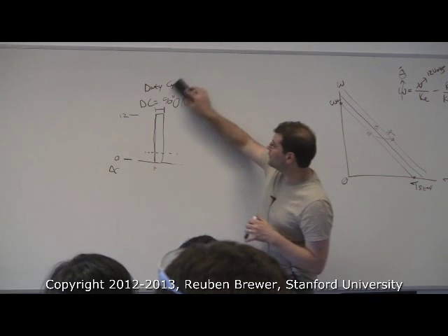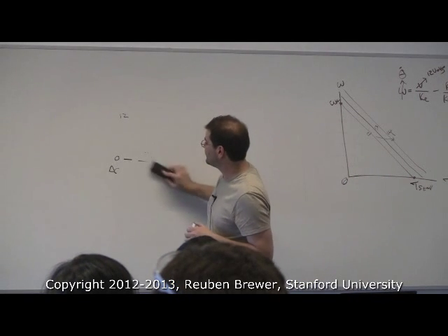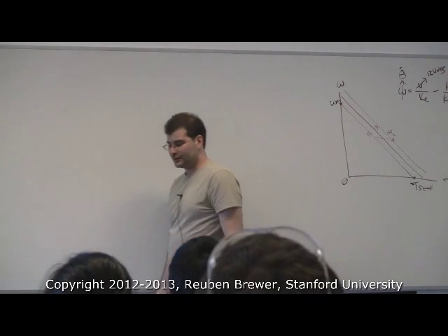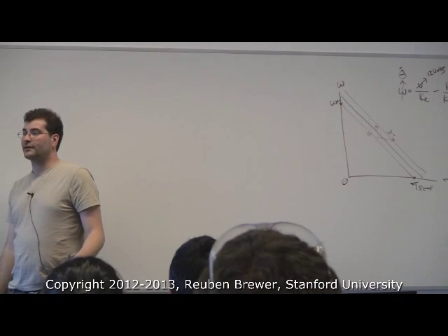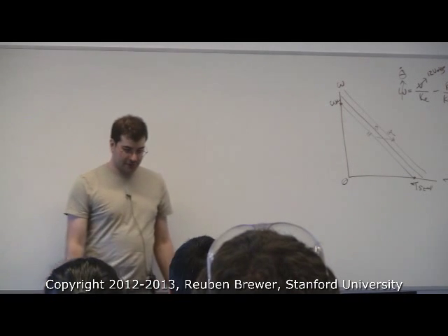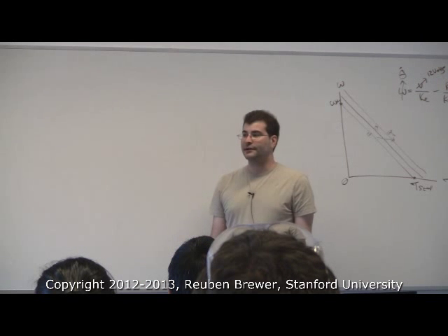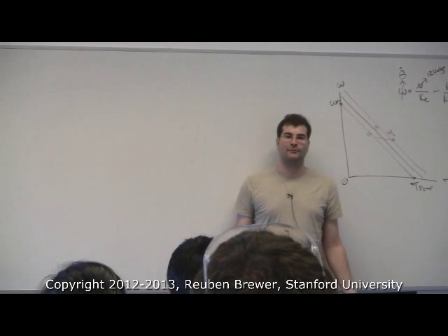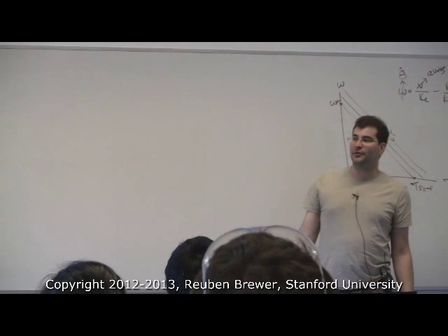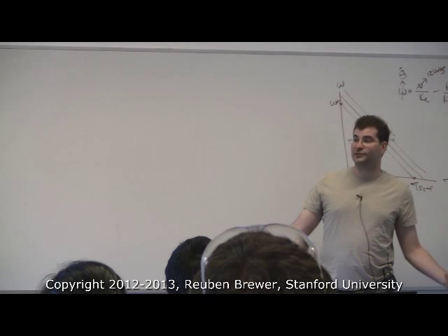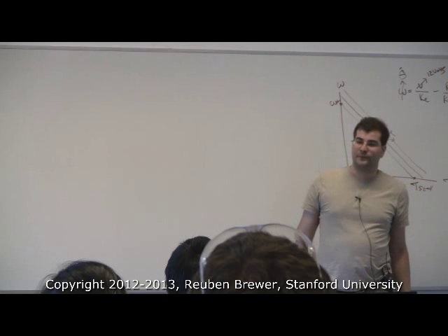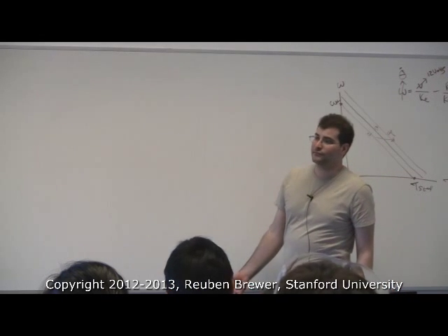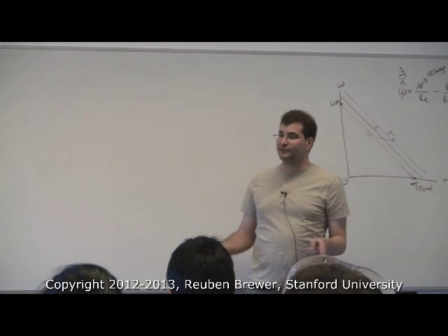The reason why I'm being a bit glib about that is typically you're going to be somewhere around, I think, 20 to 48 kilohertz in terms of what you're doing practically, because hopefully you're not programming your own PWM signals anyway. Hopefully you've bought an amplifier, and the amplifier is going to be a black box where it simply runs at some PWM frequency, and that's what you're going to use because that's what it's hard-coded to be. And if it's an industrial grade amp, and it's good in all the other specs, then it's going to be fine for that.